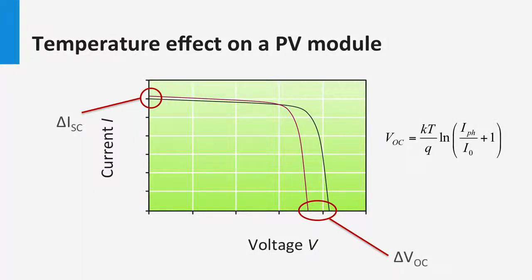The decreasing effect on voltage can be explained from this form of the basic diode equation seen in the earlier weeks. While the temperature affects the various terms in the equation, the net effect of temperature is that it decreases the open circuit voltage linearly. The drop in open circuit voltage with temperature is mainly related to the increase in the leakage currents of the photodiode I0 in the dark with temperature. The I0 strongly depends on the temperature. We have dedicated one of the exercises this week to this effect.